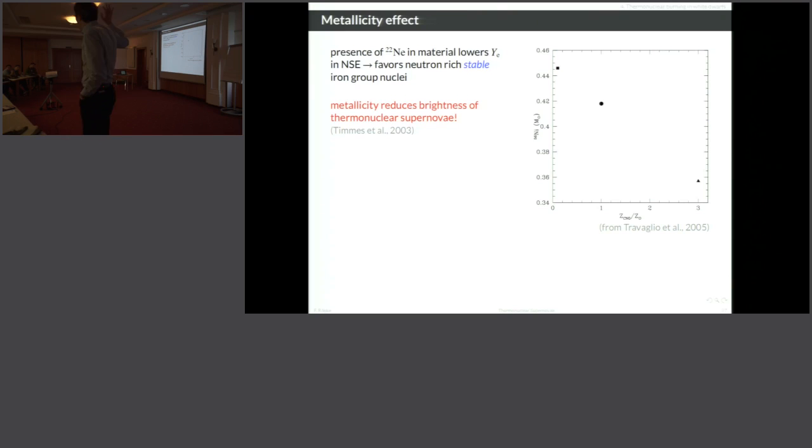All the theory we have on detonations is a 1D theory. There's no multi-D theory on detonation ignition and detonation propagation really existent. So therefore, this is a rather complicated topic. In multi-D, it may be that you have this complicated cellular pattern with the triple points. Some people explain it that way, that only in a triple point the shock is strong enough to really lead to reactions, so that the detonation is quenched in between. It's always reignited in the triple points, and this is how it propagates. So rather complex internal structure of multi-D detonations.